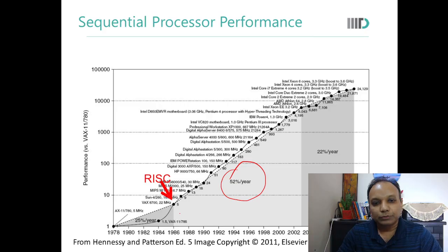The introduction of RISC actually made the hardware more modular, more streamlined. You could implement better pipeline strategies because of the uniformity which RISC provides. In RISC, all of the instructions are of the same pattern.